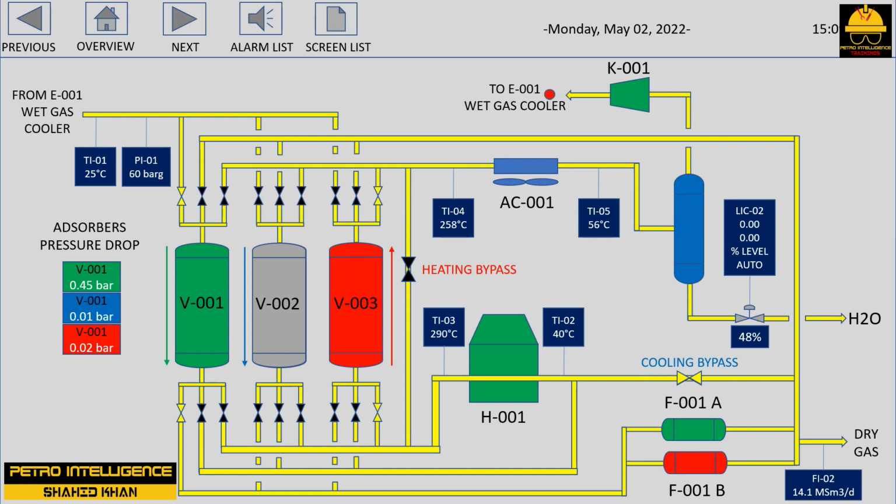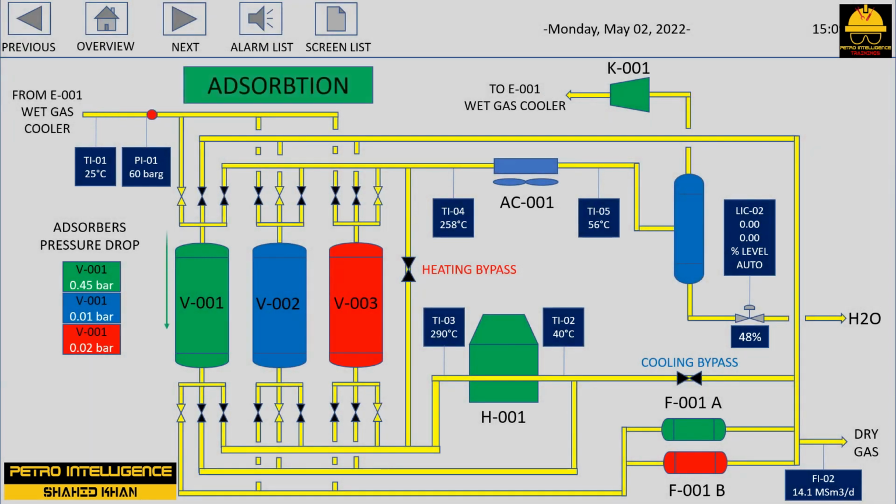The fixed bed type is by far the more common adsorber. It contains some type of bed support mechanism to hold the bed in the vessel. This would typically consist of some sort of grid support covered by a wire mesh screen. In some cases, the screen is then covered with graduated sizes of gravel or other solid particles to support the adsorbent. Such support facilities are needed to prevent the very small adsorbent particles from being washed out of the bed.